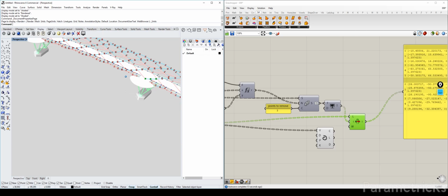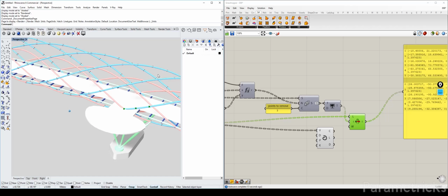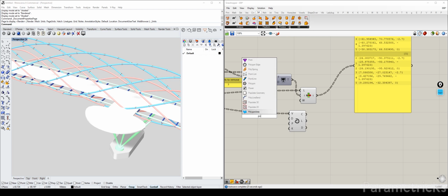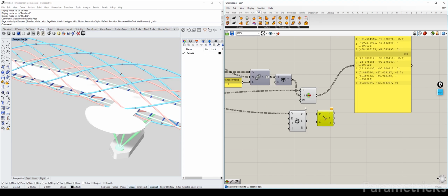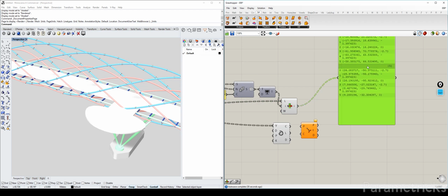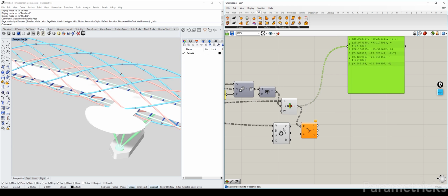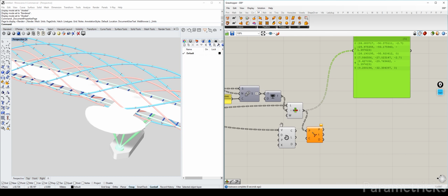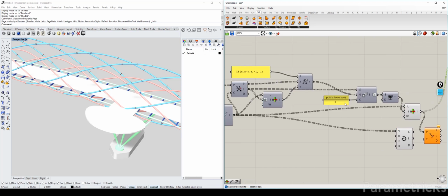The next step is, now that we have the points that should be called, we can say point closest to curve because we want the t parameter, because we want to shatter our curve. So all this is to find the points that are on the curve, because that's where they come from. But what we don't know is the parameters of those points. That's what we do all this to identify.